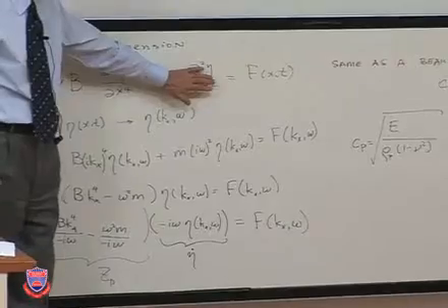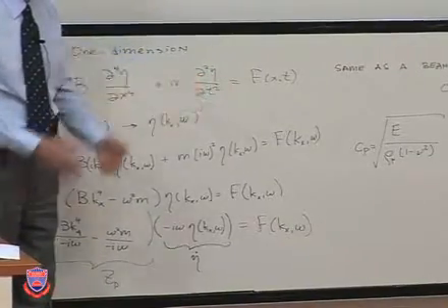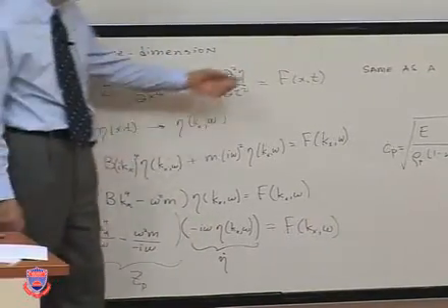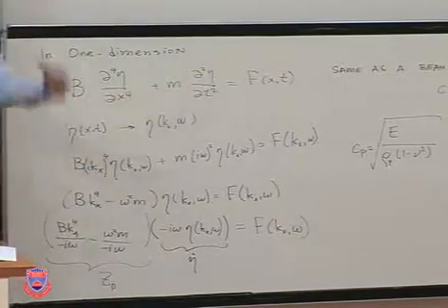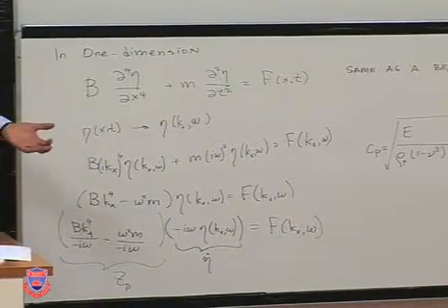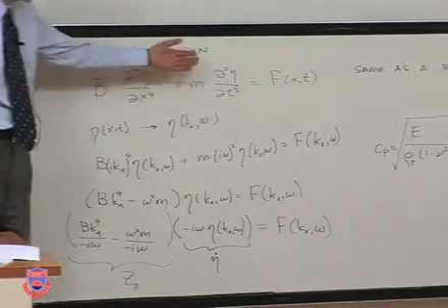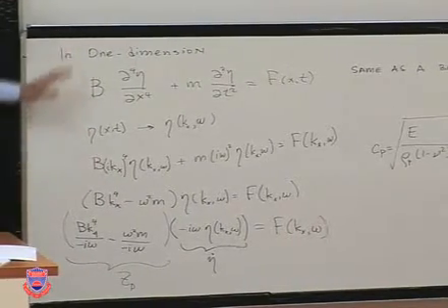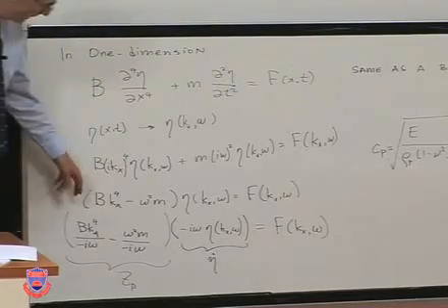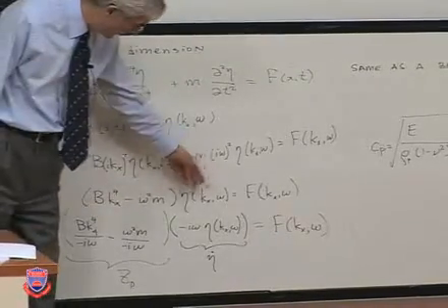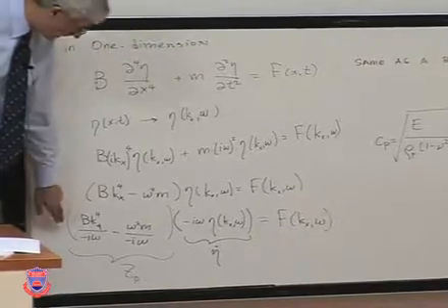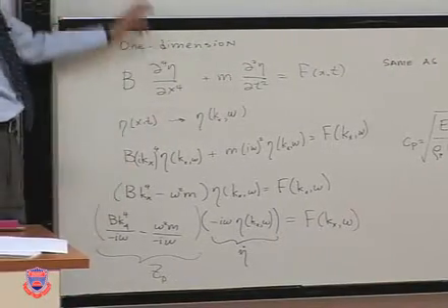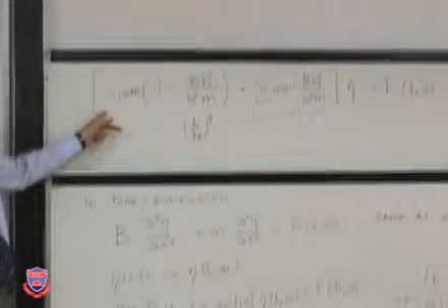We have a force per unit area due to plate inertia and a force per unit area that's acting on it. What's a force per unit area? It's a pressure, okay, acting on it. And to solve this, an easy way is to express everything in the Fourier domain, and then we have an impedance expression. This is without any damping in the system. This is with damping in the system.